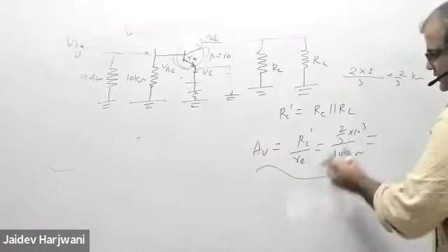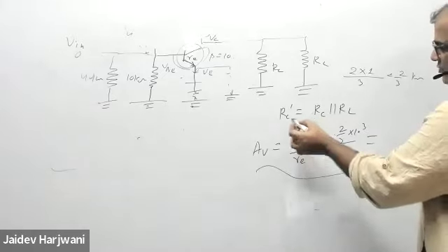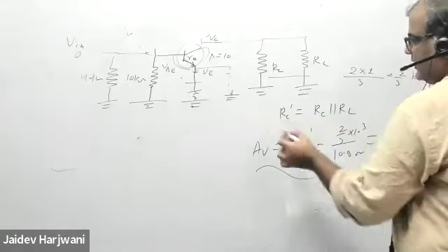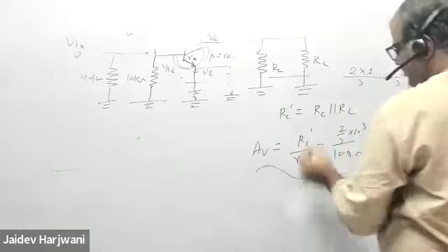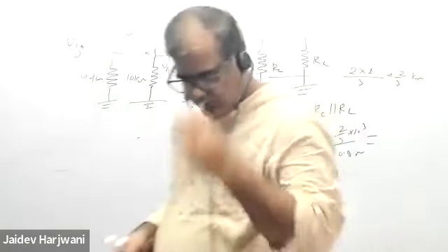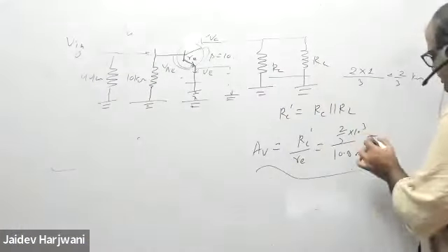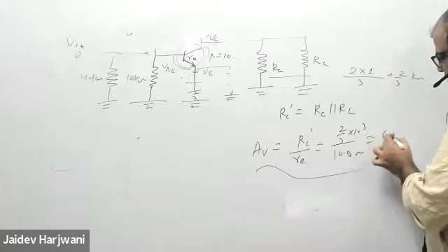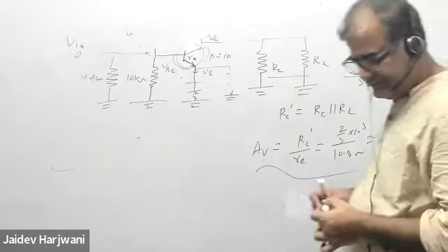Okay, so this is the formula now, and you know the RC, this will be this one, and RE we already found out. This is the formula. Put in the values, how much is coming? 61.7. So around 60. This is around 60, the gain of the circuit.